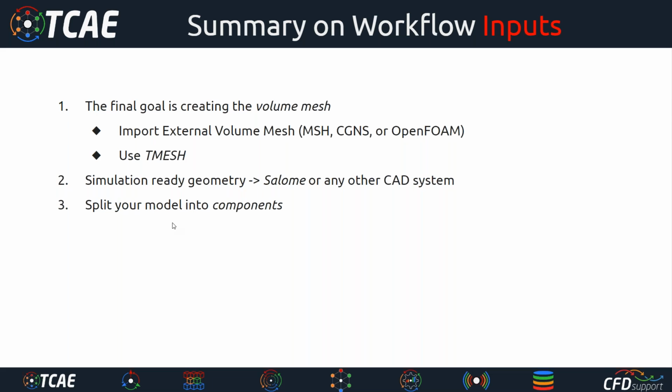So we technically make its own mesh for it, because we want to be able to allow it to rotate. Even if we use static methods, it's smart to have this option to let it rotate. And then it can be, for example, the spiral and the outlet tube. So you can have any number of components. But what is important is this component thinking, right? So you split your model into components.